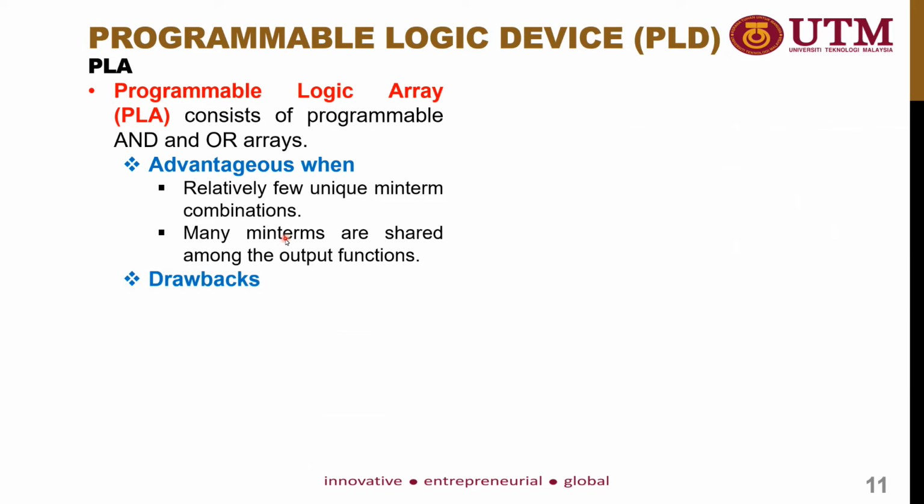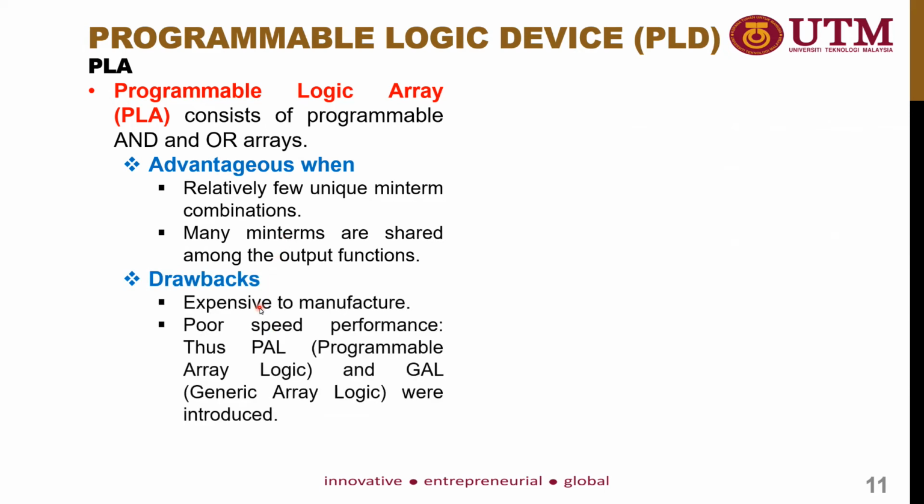And the drawback of this PLA is that it is expensive to manufacture because it has a lot of programmable interconnections. Alright, so it also has poor speed performance. Thus, PAL and GAL were introduced because of the poor speed performance of PLA.